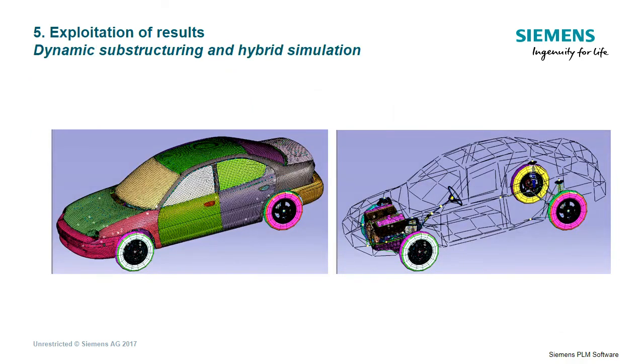It is also possible to combine two modal models and predict the response of the coupled structure. This can be useful when we need to understand the influence of different variants of the same component on the behavior of the full system, without having to assemble and physically test it. This can be performed with either numerical and/or experimental models.